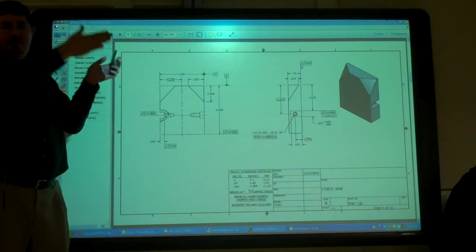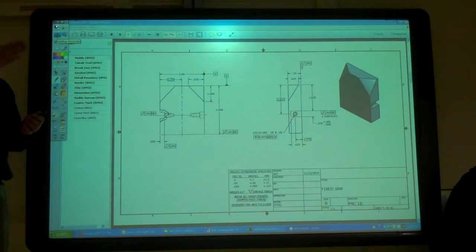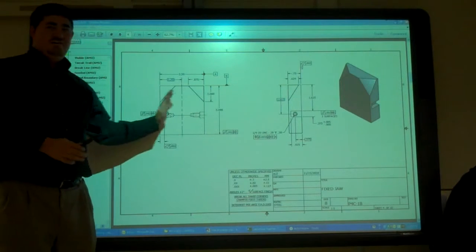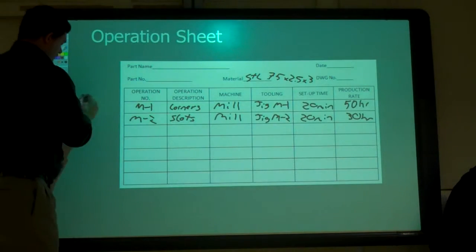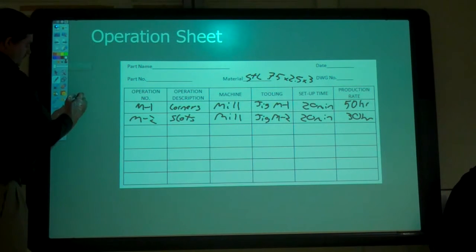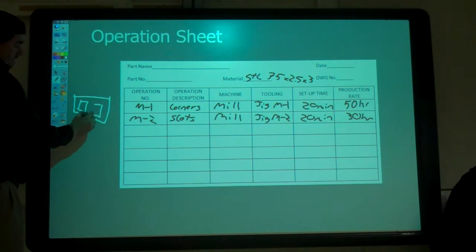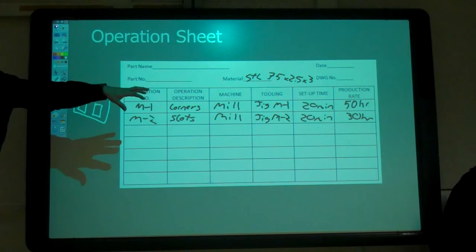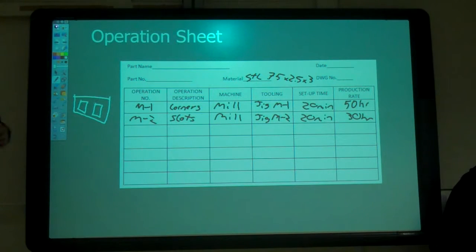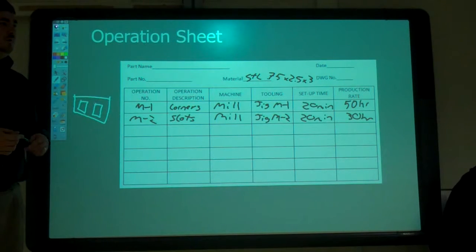And we'd still have another 2-position jig, because that's really specific. So instead of doing all the left side and then all the right side, you do a jig where you've got the jig set up. You got a slot here for one and a slot there for another one. Or even maybe you got multiple, 2 for the left side, 2 for the right side, whatever it takes to fill up the table in the middle. And that way you just load it, you hit go, it does more than one part at a time. And you take all the parts out, put a whole new batch in. Then you can have the machine running longer at one time.